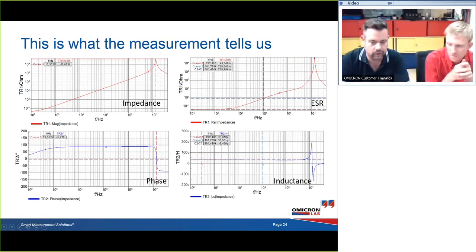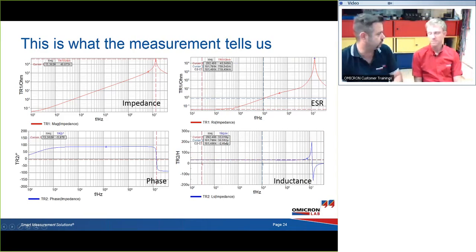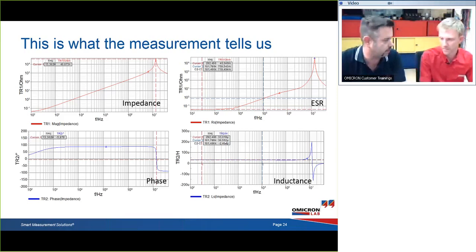And finally, if we look at the inductance itself, we see that it has 33.019 microhenry. So that's perfectly nice. Measured at 290 hertz, and if I look even at 100 kilohertz, it still has 30 microhenry. So it's well within the range defined. So it's a high quality component. Would not have expected anything else from this manufacturer in any way.